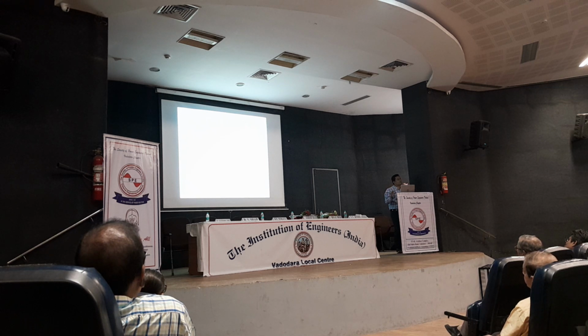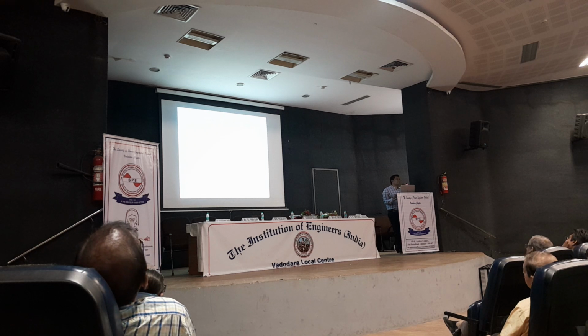Similar way you can display the cost and this voltage information, bus angle information. You can display it in two different ways. One is in per unit. Let's say if you want to display the fault current or the ampere rating, you can display it in two different ways: one is the per unit system, one is the ampere system. So that kind of feasibility and flexibility is there. So analysis will be extremely simple and easy to handle.